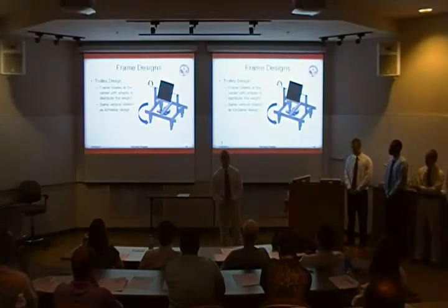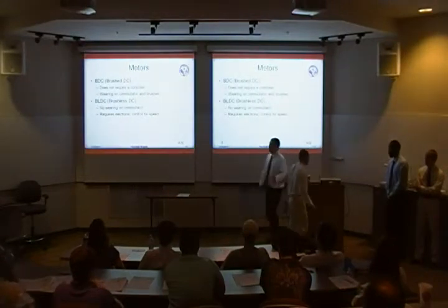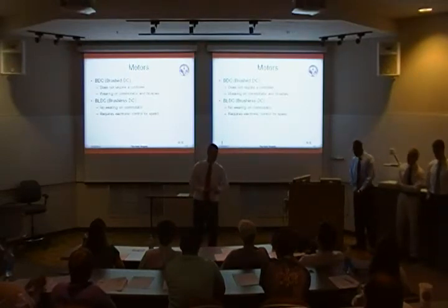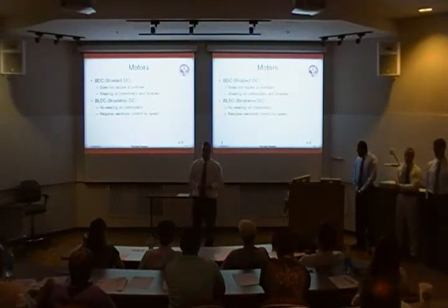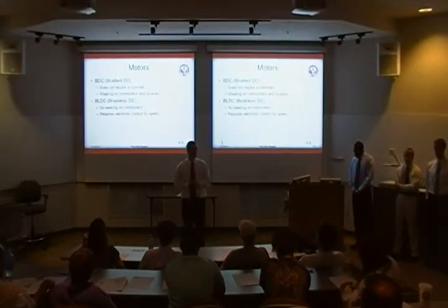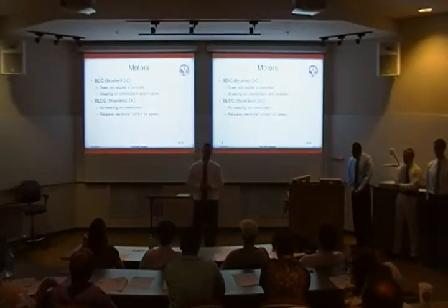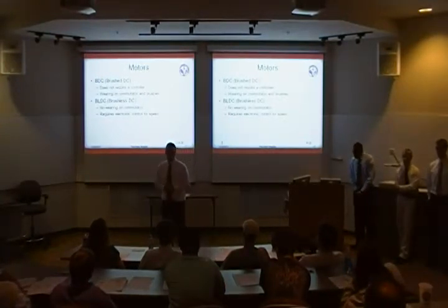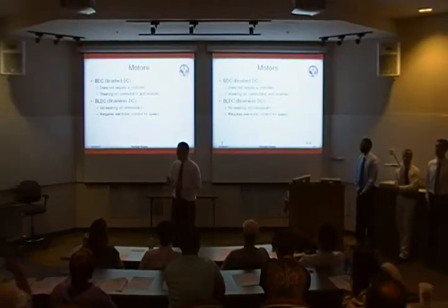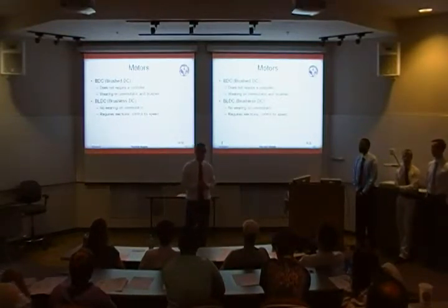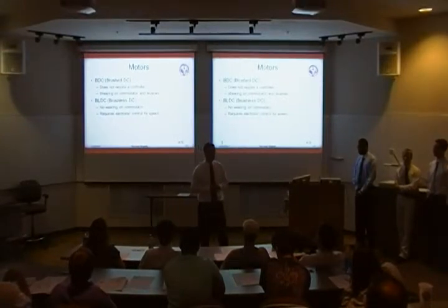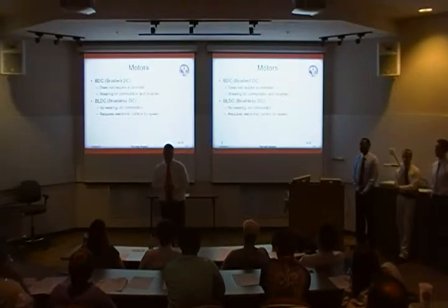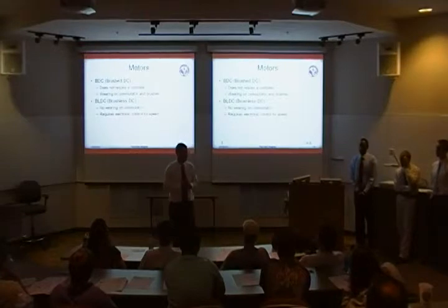And now to talk about those motors, here's Sean Reams. In the scope of our system, we were looking at DC motors to achieve our self-sustaining system, and first on the list would be a brushed DC motor. Brushed DC motors are nice because they don't require an elaborate controller to control them, but there are other options outside to control them. But unfortunately, brushed DC motors also have the highest maintenance of the motors that I'm about to explain. Brushless DC motors overcome the wear by implementing commutation with an electronic control. But they also require some electronics for speed and position.